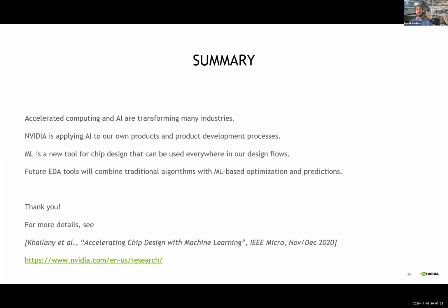world. So in our case, the environment side depends on what you're doing. If you're trying to do layout, the environment may be evaluating DRCs or LVS, so that has to run really fast. If that runs on a CPU and is slow, then it might be hard to train a reinforcement learning engine. So in some of these cases we might need GPU acceleration of traditional algorithms just to make the reinforcement learning optimization loop work. That's one of the reasons we're excited about these GPU accelerated placers: given the huge amount of compute we can throw at the problem, they can do placement in the loop as part of your environment simulation of decisions you might make. So hopefully that answers your question, or at least as well as I can.